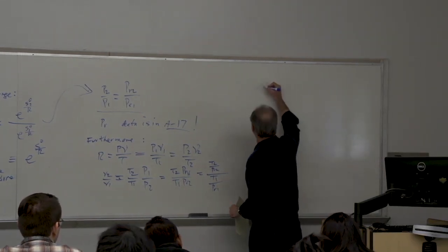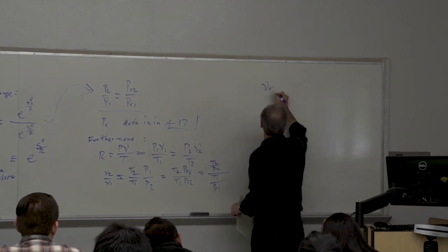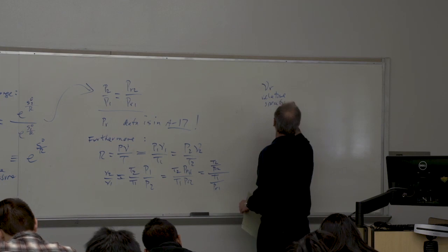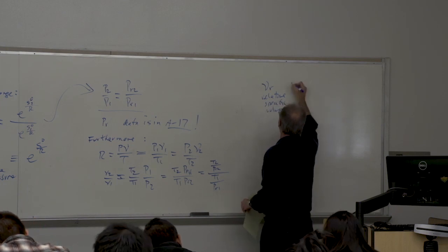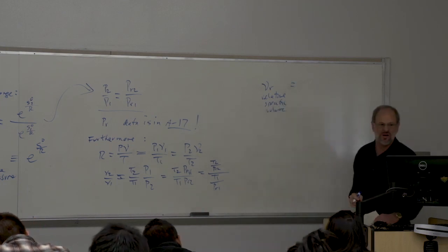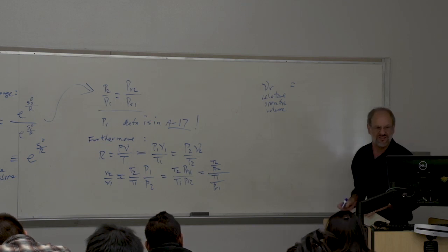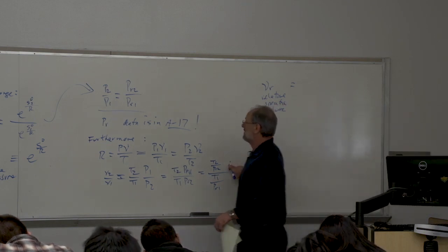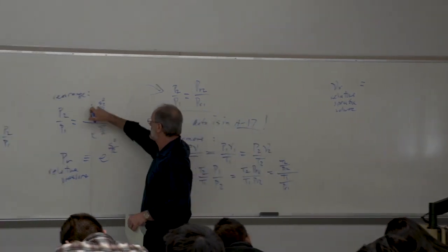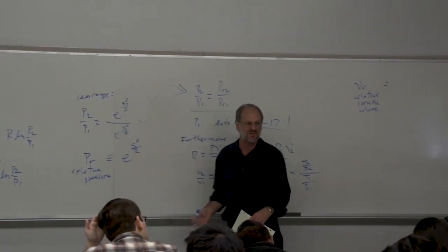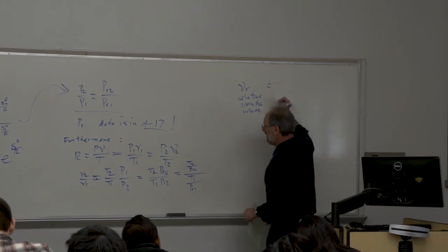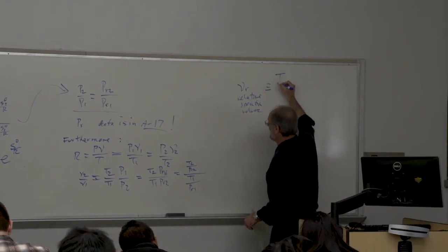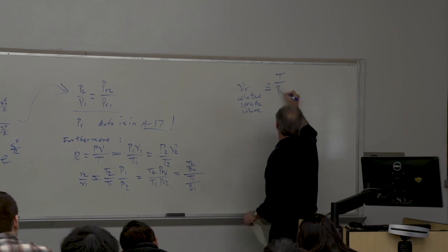That's going to be called vr, which is the relative specific volume. It's not even a specific volume term. It's just another entropy function, isn't it? Or really a temperature function based on the relative pressure, which is of course based on these entropy functions. It's only a function of temperature. So vr is going to be defined as just T over Pr.